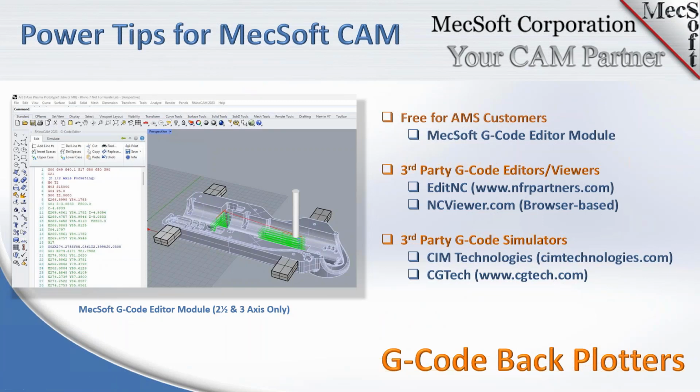Now let's talk about G-code backplotters. Why might you want to backplot your G-code? Well, typically this will come into play if you're getting an error on your machine. Say it's stopping at a certain line and you get an error message, and the controller machine won't cut any further. So you need to resolve that error. In order to help you debug what that error means, you need to get into the G-code. Typically any error message on your controller will have a line number. Where in this G-code file was this error created? So you need to go back to the G-code file, look at the line number, and see what's going on at that line that might cause an error.